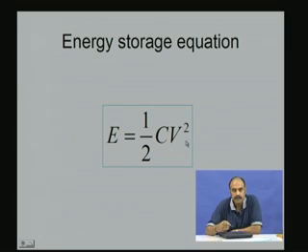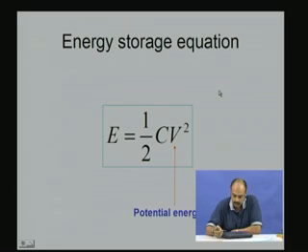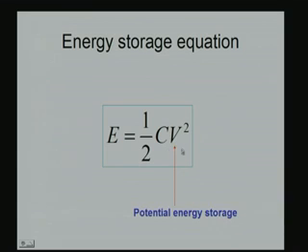We know that the wattage is V into I, and V into I into time is going to be the energy, watt seconds. So, the integral of that over a period of time will give you the energy, which is as given here. So, we say that as the capacitor has the voltage variable in the energy equation, its state variable, or the history that it can remember, is the voltage, which is the potential, and therefore, it is called the potential energy storage component.